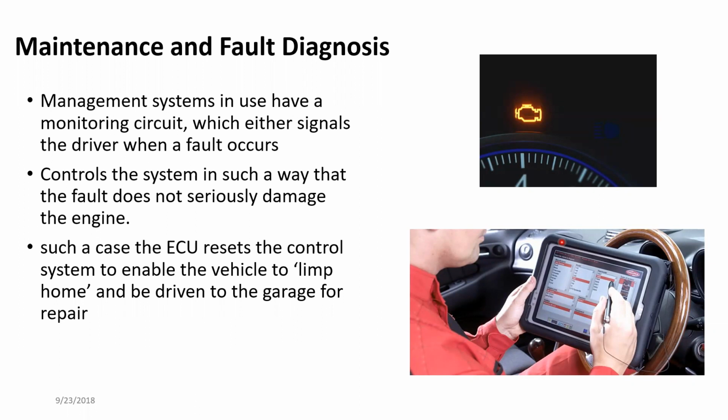Whatever value is not available is where the problem should be, as per what the engine management system understands. But it does not mean that is the exact problem. It actually gives a probable reason. So this area, this particular sensor is out. For example, this is 100% and the engine RPM is saying 300.